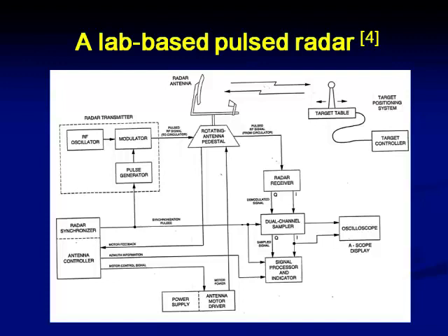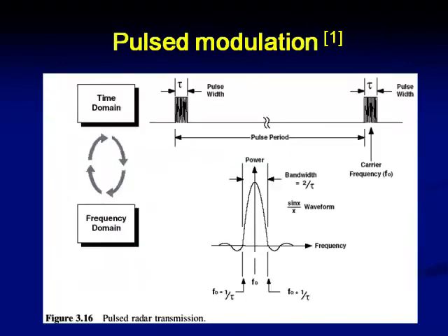And then we are going to have high power signal processing techniques. In this context we call them radar signal processing techniques, and the resultant data is now displayed on an oscilloscope like this. Why we use pulses is to see that a high amount of power is sent within a short duration, and in this the terminology used is pulses. How many we are sending per unit time we take into account, and we call this the pulse period, and the pulse is on for a certain duration which is known as pulse width.